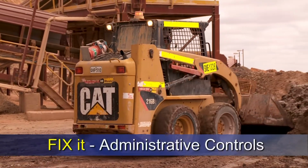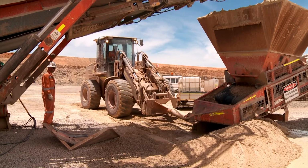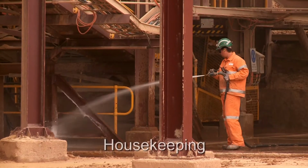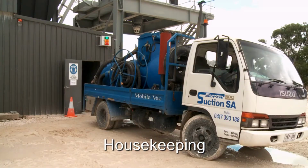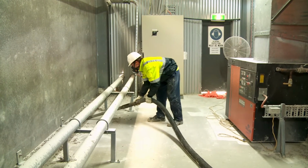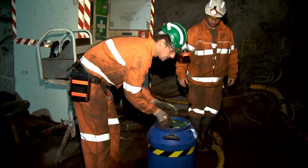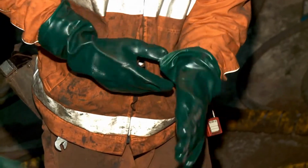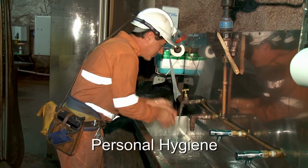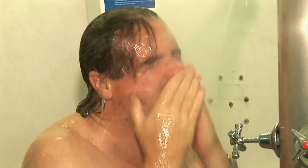Administrative controls. The impact of dust can be limited by following key administrative controls. Keep work areas and amenities clean and tidy. Do not dry sweep. Use methods that prevent the creation of airborne dust, such as vacuuming. Clean up spills using appropriate materials and methods. Wash your face and hands before eating. Shower at the end of shift.